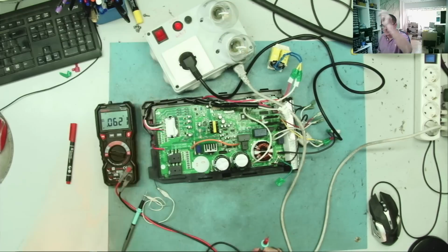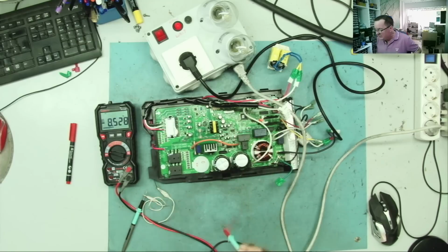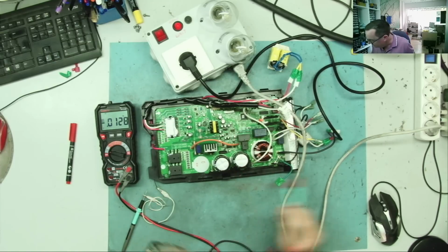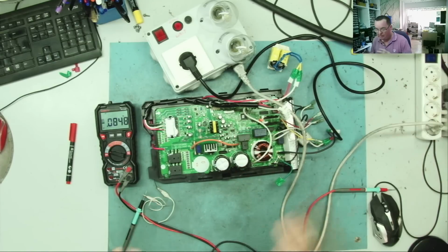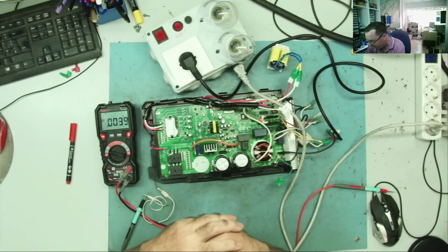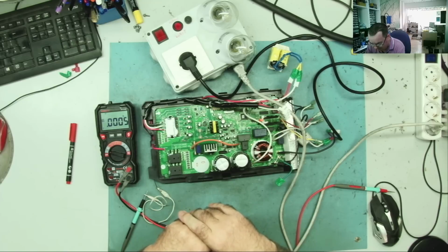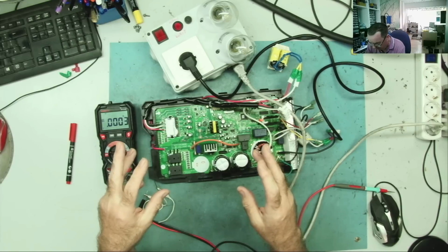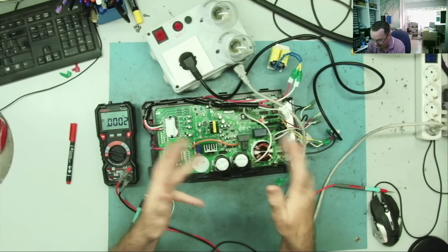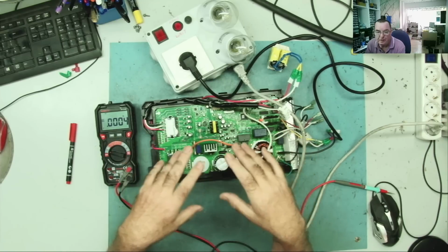Okay, I'm going to switch the limiter out, so we're directly on mains. What do we have? We still have minus 9. So, that is still a mystery. Why? Then we have 2 things to investigate here. One is, should it be plus and minus 15? I'm guessing they should be the same. And secondly is, is there a problem with the firmware? Maybe that is a red herring, so we need to figure out also how to find some firmware for this.